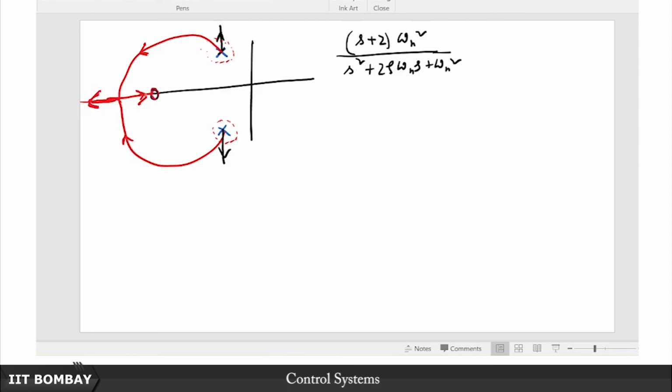but here I know that in the vicinity of this additional 0, it must approach the 0 as k tends to infinity. So therefore in between somewhere this reversal must happen, so there is a break in that must occur, as indeed you will see if you actually apply that condition for computing the break in point. You will see that there is a break in point beyond minus z. So this point is minus z, and a break in point occurs beyond minus z. All of this can be deduced just qualitatively without even any computation.